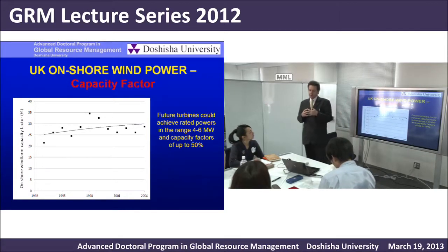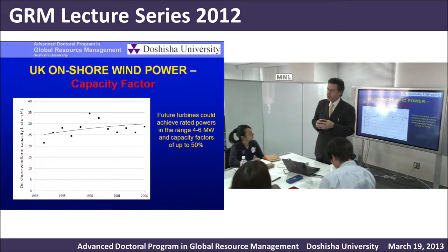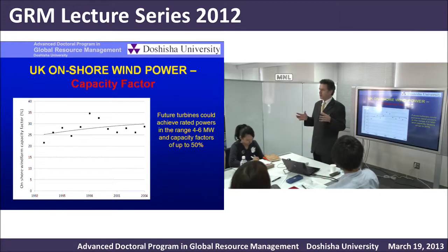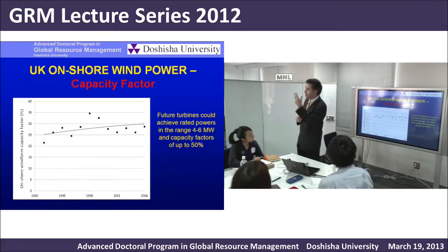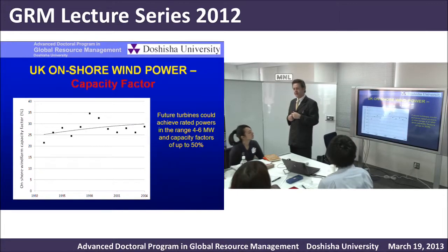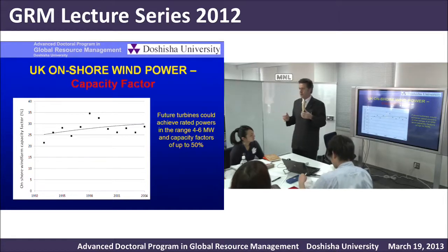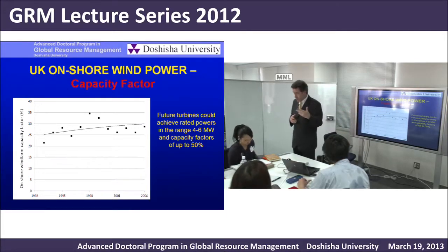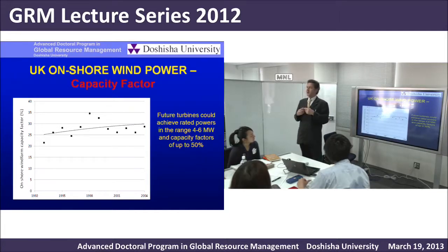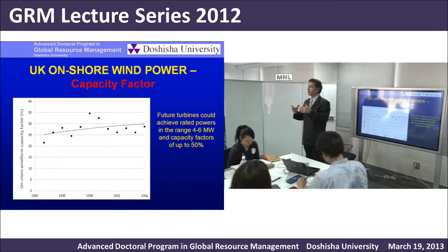And a measure of the amount of energy that a wind farm produces as a proportion of the total theoretical maximum, the maximum being if the wind farm is on full output 24 hours a day, 365 days a year. So we have something that's called the capacity factor, which is the ratio of the energy actually produced to the potential maximum energy yield in 1 year. There are different ways of calculating the capacity factor, and sometimes it's called the load factor. You can measure it accurately from the energy metering, which is the most accurate. You won't tell a lie when you know what you're getting from the farm.